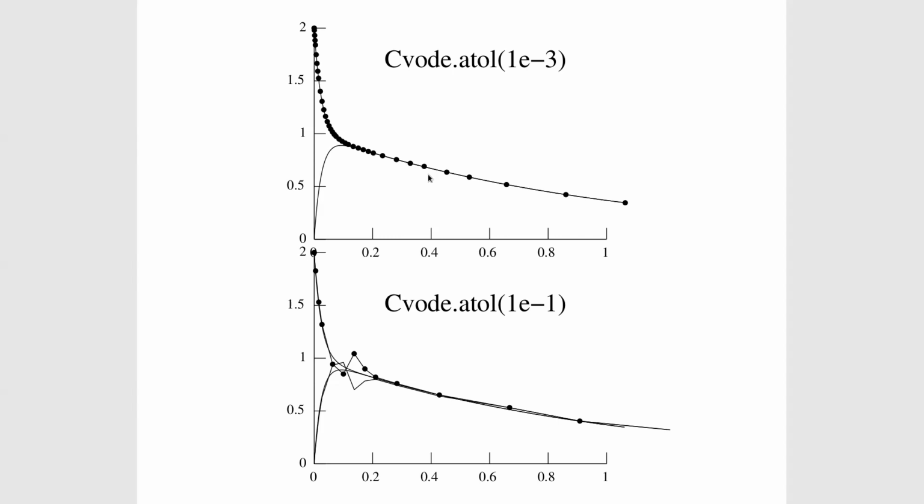Very nice looking solution. Okay. You can get a little bit of speed up if you relax the error tolerance, but watch out, because if you make the error tolerance too sloppy, you'll get bizarre stuff like these weird overshoots and peculiar oscillations. Okay? And if you start to see any of that instability-looking stuff in your solutions, it means your error tolerance is too loose. You need to change it. Maybe you need to apply a tighter tolerance only to certain of the state variables. And Robert's presentation is going to address some of that.